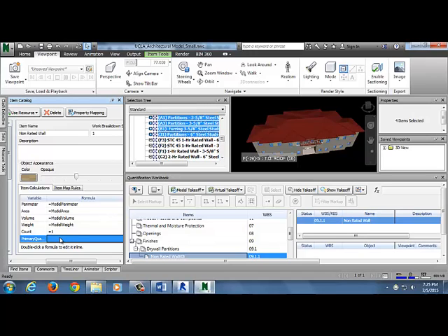And so I'm going to make my primary quantity. We haven't dealt too much with the primary quantity, I don't think. When you do your export into Excel from Navisworks, it gives you all those columns of the model width and the width, and then at the very end there's one called primary quantity. So this is a way, if you set up your catalog, to have basically one column that you just have to look at, if that makes any sense.